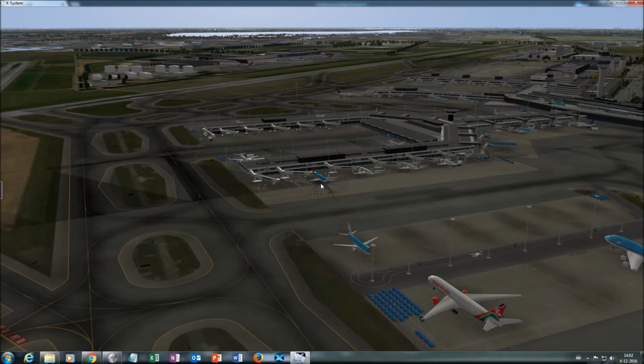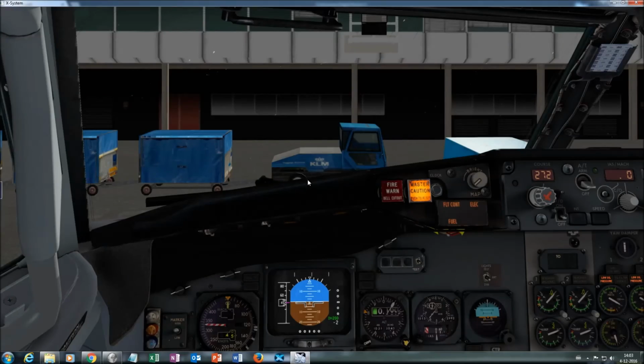So basically, you are always trying to calculate the optimum setting, within the safety margins, of course, to use as much of the runway as possible, because then you don't overstress the engines. So it's very economical. But it is very, very important. Of course, the profit margins in the aviation industry are extremely low, so every penny is welcome. And that's what you do with derating. So let's go back.